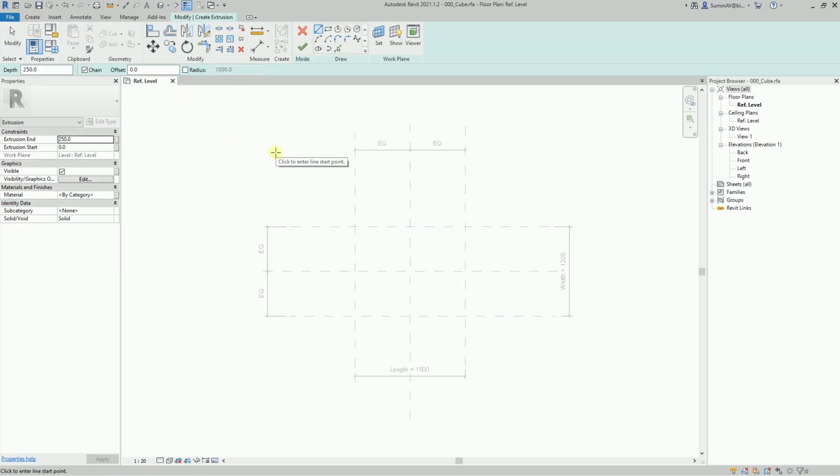Different rules apply to different Revit tools in the Edit mode, but in fact, we always have to create a flat sketch. For the extrusion geometry, the sketch will be extruded to a set height downward or upward, and thus shape a 3-dimensional geometry. Since we are creating a right-angled parallelepiped, we are required to use a sketch of a rectangle. In the Edit mode, we can see various tools on the Draw panel. These tools include the rectangle that we need.